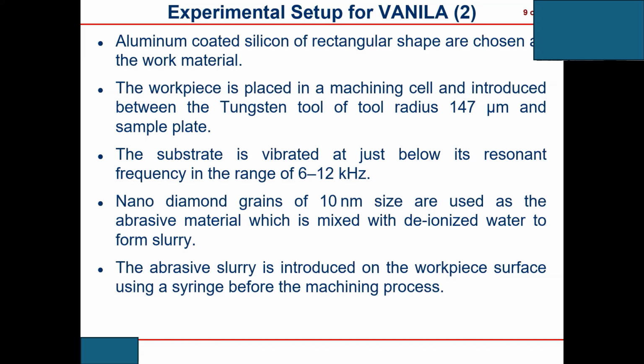The same thing. Nano diamond grains of 10 nanometer size are used as the abrasive material, mixed with deionized water to form the slurry. The slurry contains deionized water and diamond abrasives. The abrasive slurry is introduced on the workpiece surface using a syringe before the machining process.